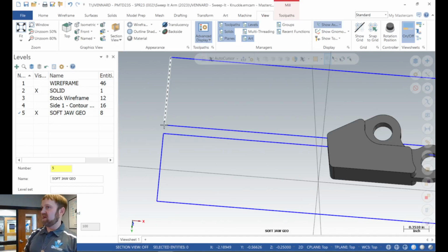I'm going to say this multiple times and I'm going to repeat it. This is the origin for side 2. Once you edge find the jaw in X and Y and you set your Z off the top of the jaw, that's your side 2 origin, even for cutting the part. It's all going to be based off that origin that we set on the jaw. What everybody wants to do is cut the jaw pocket, then put the part in the jaw, then come over and edge find on their saw cut of what's left to deck off and set their Z off the top of the part, and then want to know why everything's happening up over here. Okay?